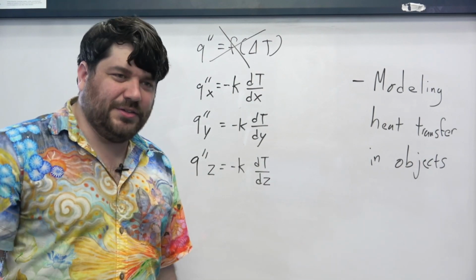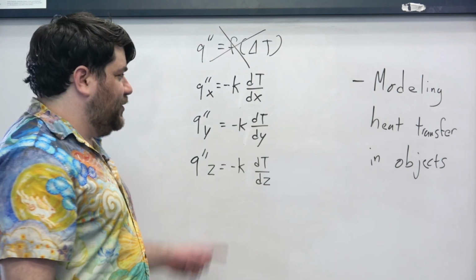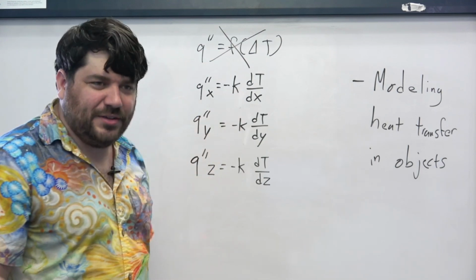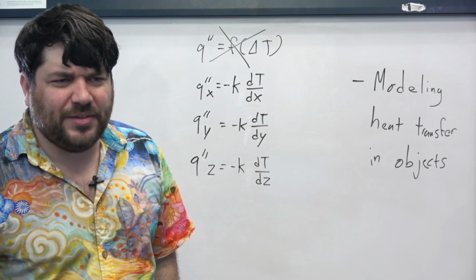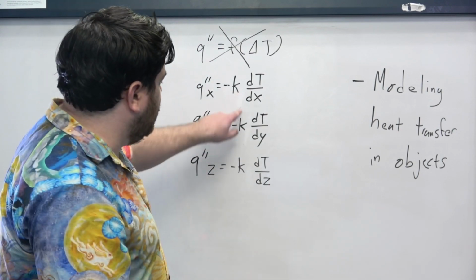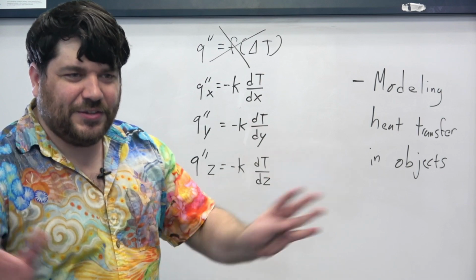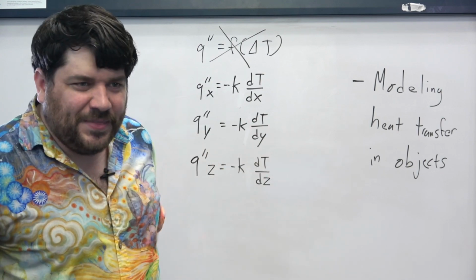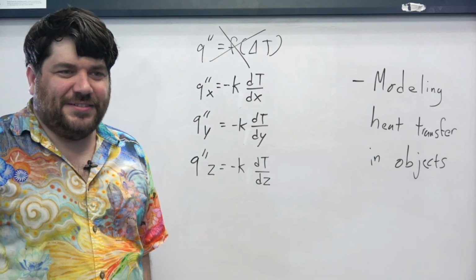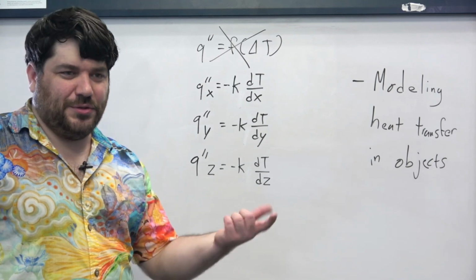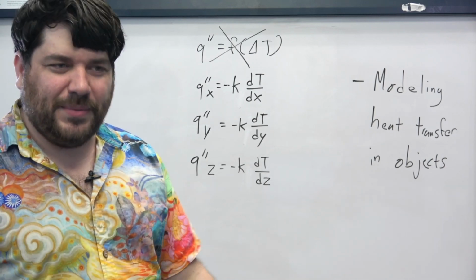But there are some materials in which that happens. And so in those materials, you would expect to have different thermal conductivities in different directions, all right? But for the purposes of what we're going to be doing for the rest of the course, we're just going to assume that the K is constant, that it doesn't change as a function of X or Y or Z, that it's not dependent on which orientation you choose to put the material in, like there's no weird microstructure, okay?